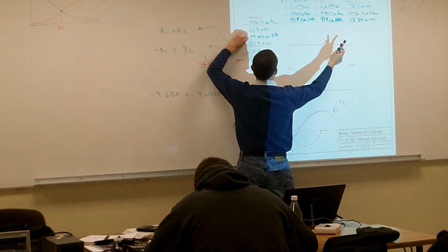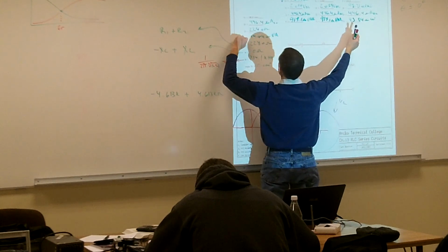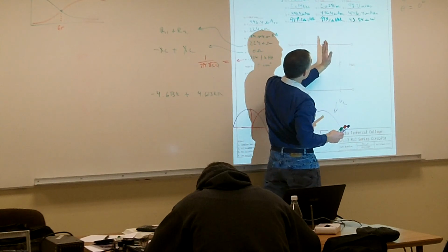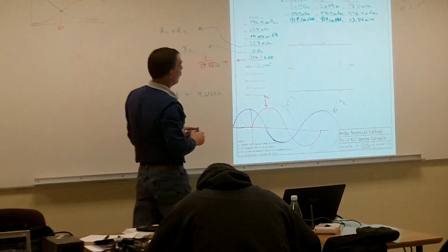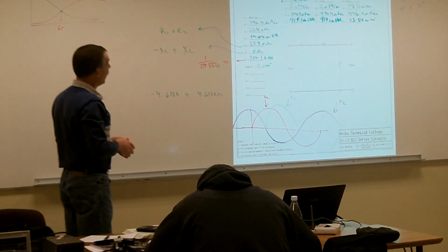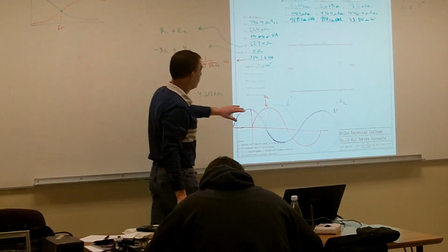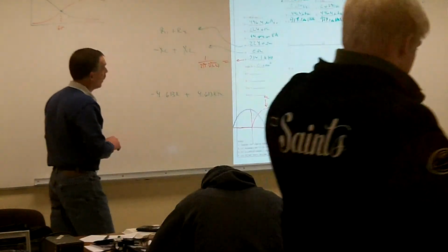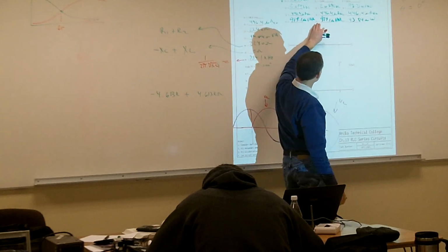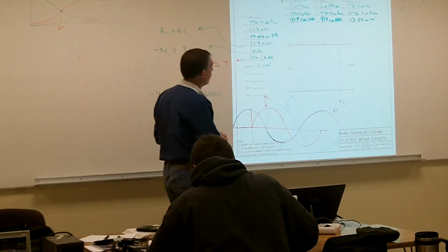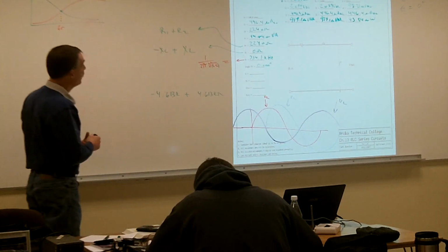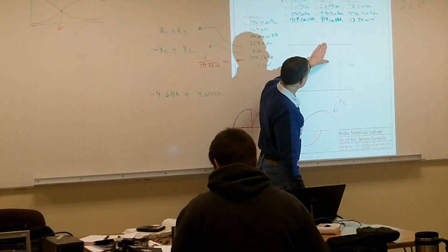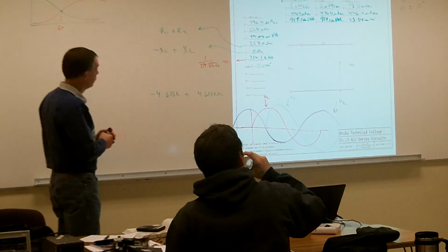So in an ideal inductor, this PT and PR would be equal. But since we do have a little bit of the true power being lost across here, that's where the remainder amount of power is going, across that inductor. That would be what causes that inductor to heat up. The only thing that would cause that inductor to heat up is the resistance of the winding. That would be our true power going across the winding. Otherwise, this power, remember, is just apparent power. It's not producing any heat, light, or any other type of energy. But since we do have a little bit of resistance and a little bit of power being dropped across it, that inductor will heat up just slightly, depending on the size of it.